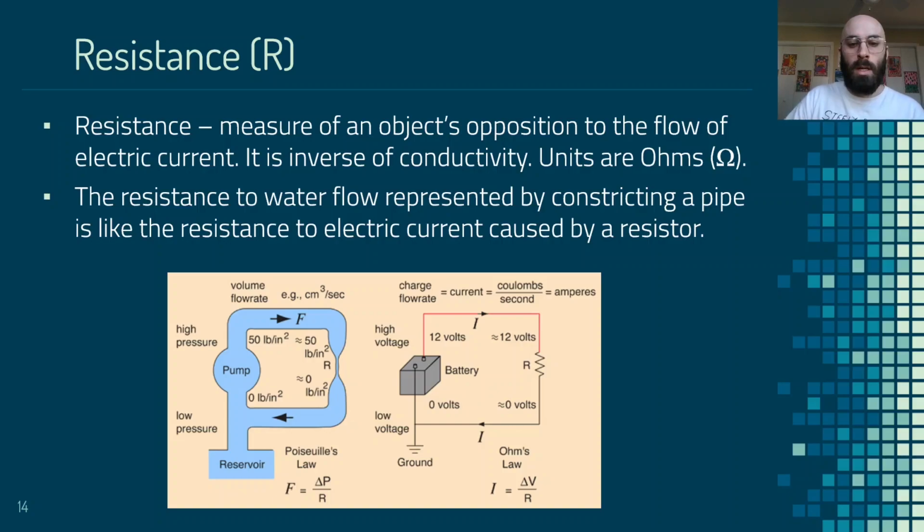And so the flow of the current is actually inversely proportional to our resistance here, right? So typically we have a fixed voltage coming from some fixed voltage source. Like we'll be using 9-volt batteries, which will provide a constant 9 volts. And so what is going to change in our circuit is the current, based on the resistance, or based on what we introduce into our circuit and its inherent resistance. So as the resistance goes up, our current will go down and vice versa.